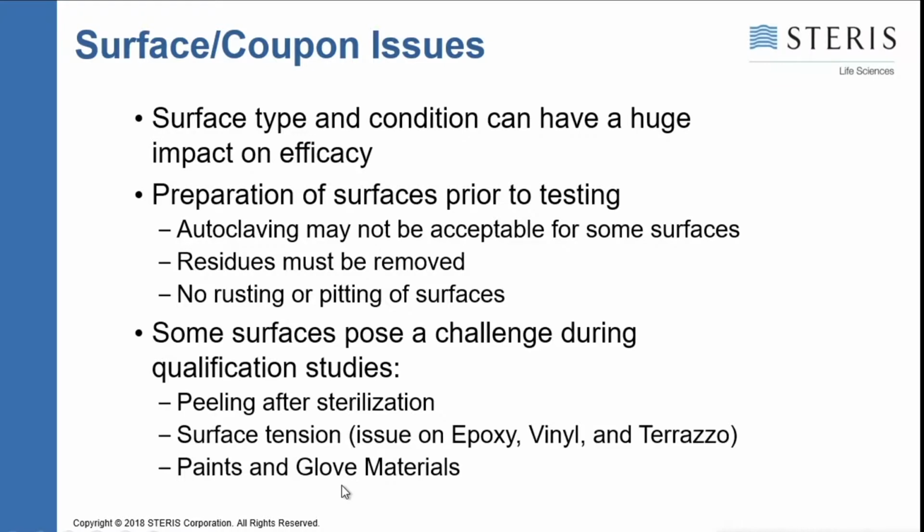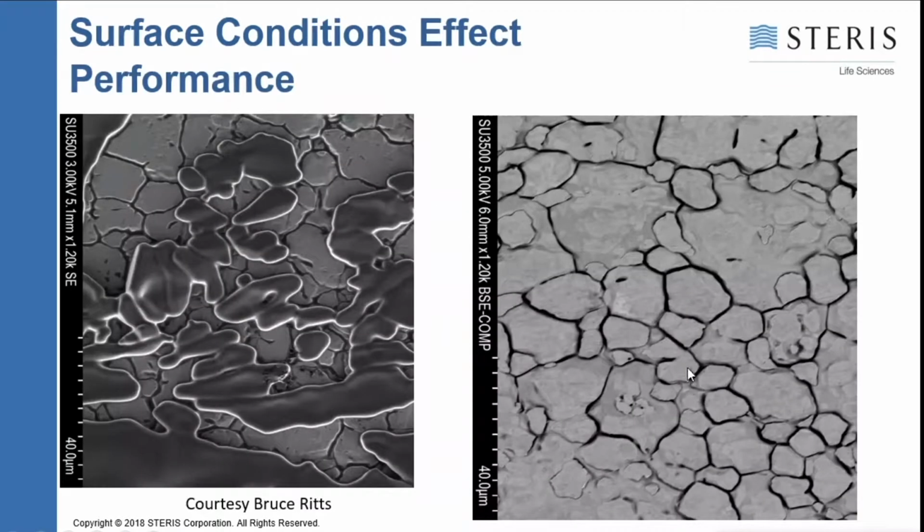So here's a close-up of 316 stainless steel. You can see it looks like the Mojave Desert or the Sahara Desert here. But when I do add disinfectants to it, it does leave a residual. So that surface has got to be clean. You would need to clean it, and then you would want to sterilize it too, either through autoclaving, VHP. There are different ways to sterilize it, maybe a liquid sporicide, but that's a key thing.